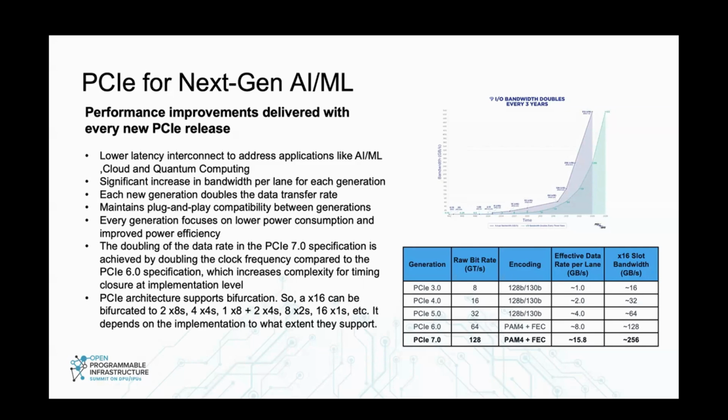Here, what I want to highlight is that the PCIe architecture is backward compatible, and it can also support bifurcation and aggregation of the logic. In my next slide, I would cover what I mean by bifurcation and aggregation. Here, if you take an X16 link, it can be connected into two X8 or four X4, or it may be connected into multiple combinations of X4.